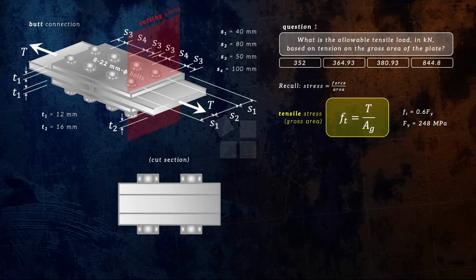Therefore, the thickness you'll consider should not only be 12 mm but 12 times 2, which will give you 24 mm. Notice that the thickness of the middle plate, your T2 as 16 mm, is significantly less compared to the top or bottom plates, whose thickness must be 24 mm.